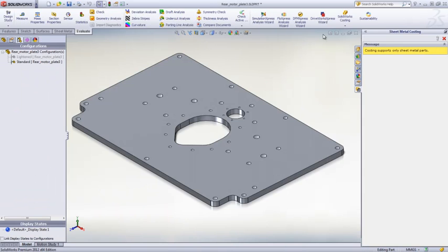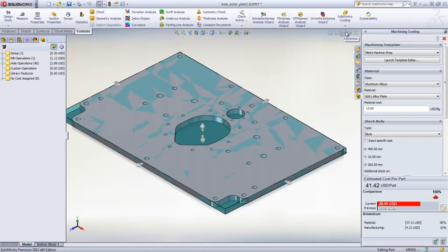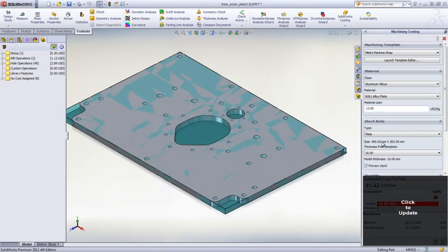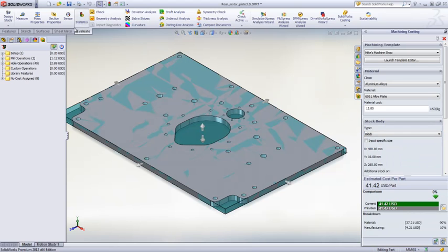Let's now take a look at a machined engine backplate. Costing automatically switches to a machine template and calculates the cost. You have the ability to choose if the part will be machined from a solid block of material or from stock plate. Part features are sorted into cutting, milling, and hole operations. Tooltips explain the calculations used for estimating cost and the time.